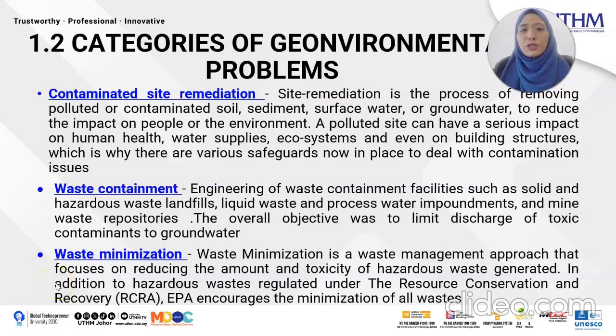Now we proceed with the categories of geoenvironmental problems that often occur to the geoenvironmental engineer. The first one is contaminated site remediation. Site remediation is the process of removing polluted or contaminated soil, sediment, surface water, or groundwater to reduce the impact on people or the environment. The second one is waste containment, which means moving all the solid waste, liquid waste, and other waste to the landfill area in order to limit the source of toxic contaminated groundwater.